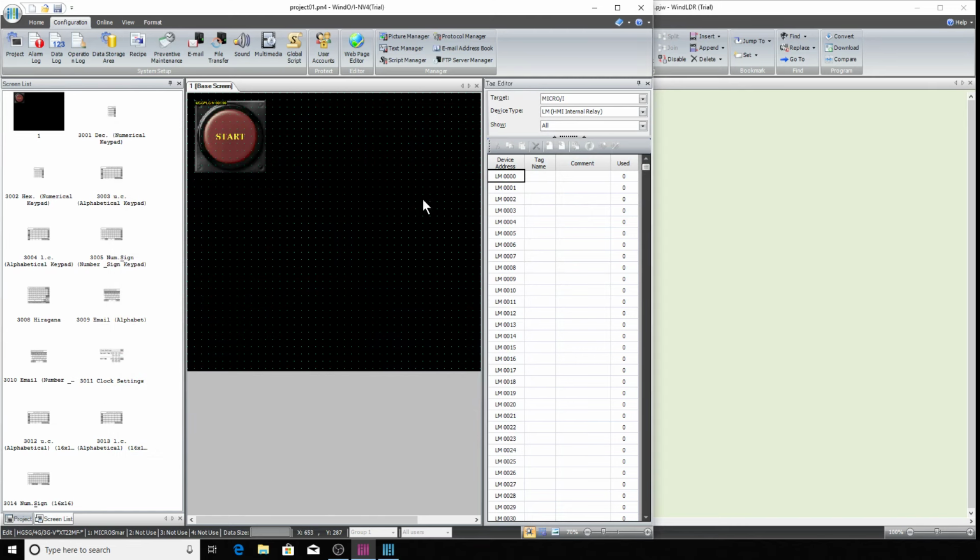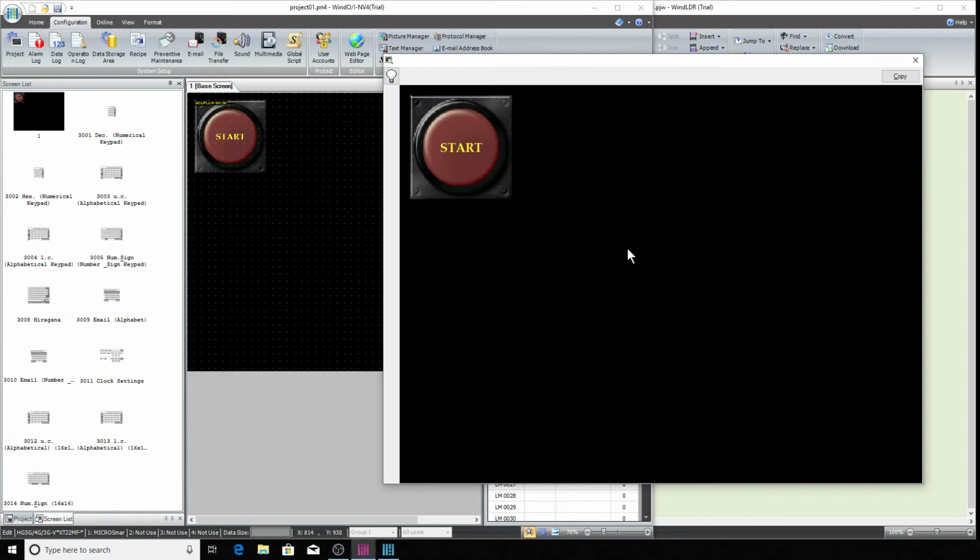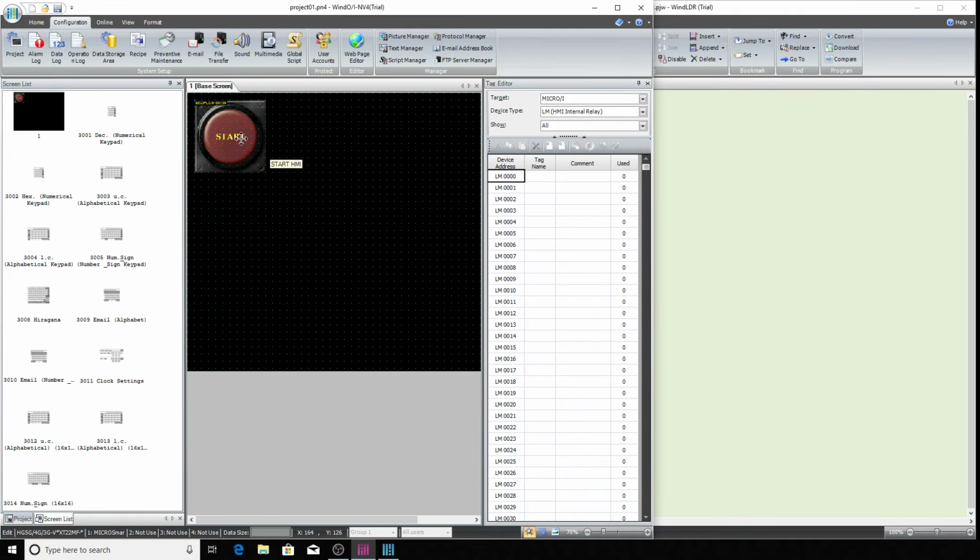It's better. Okay, preview of it. Let's get a preview. That's what it looks like on your HMI. When you click this little button right here, that's a preview of what your HMI is going to look like. Because your HMI is going to have all these grid dots on it. The dots are for you to align stuff up, and you can make it snap to dot and all that. That's what these are, snap to grid. All right, and this is where you change states of what it would look like on your HMI. Okay, there's on, there's off, there's on, there's off. Okay, to give you some kind of an idea.